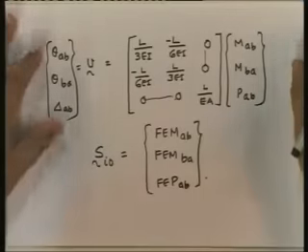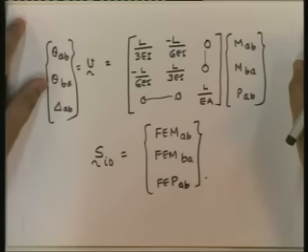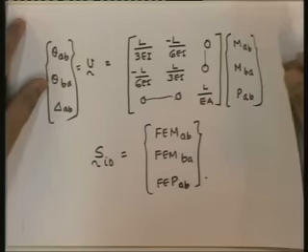Okay, so this in a sense is the overall picture, but by and large, since these are uncoupled, we do not consider flexure and axial together, and that is the reason why, if I go back to the problem that I was looking at, I have one member which is an axial member, and therefore the axial member only has axial force, and this is EA upon L. Okay. Now, so we've written down, so we have 4 members, 3 degrees of freedom.